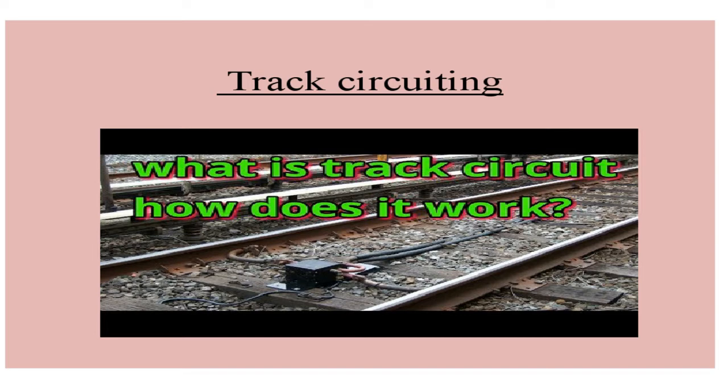So nowadays all the railroads are using track circuiting, and this kind of track circuiting is also used where automatic signaling is used. So as I have told you, this is an electrical device which determines whether any section is occupied by any train, by which the automatic signal changes its aspect. Aspect means you know that we are having 2 aspect, 3 aspect, 4 aspect like that.